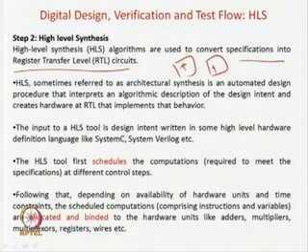High level synthesis actually converts specifications to black box type of blocks like adder, subtractor, registers, up counters and down counters, so it is very near to RTL design. RTL means register transfer level, that is, how data will be flowing between two registers. We will solve using examples. That is why high level synthesis is sometimes called architectural synthesis. We just say in blocks: adder, multiplier, divider, registers, interconnections between them and so forth.